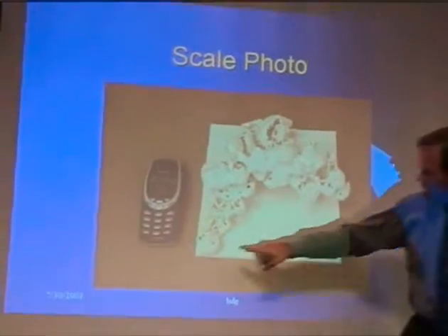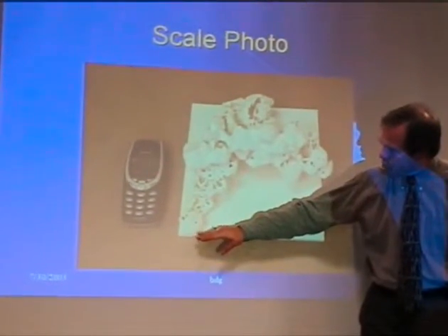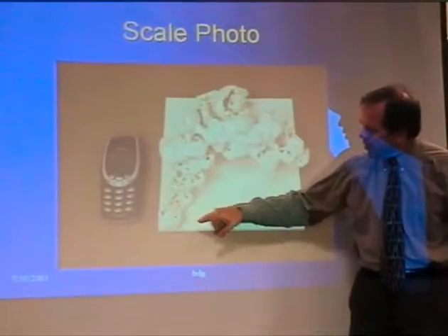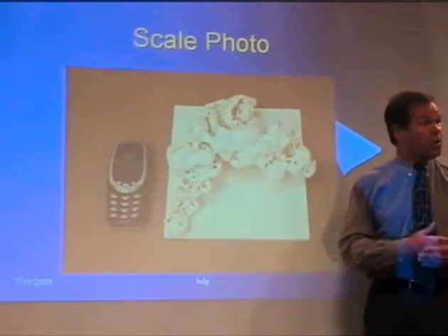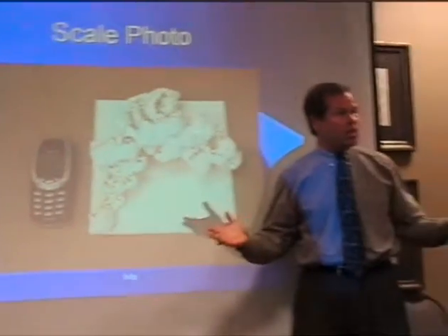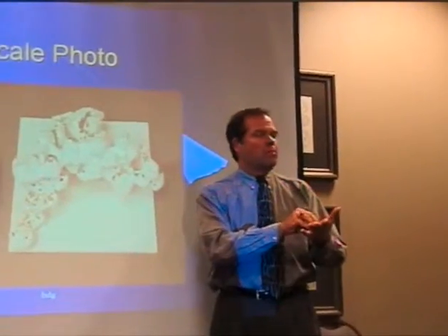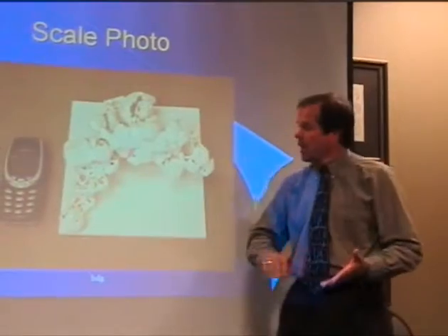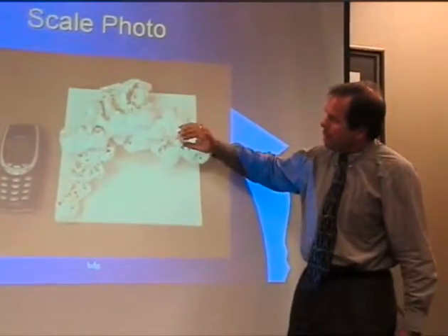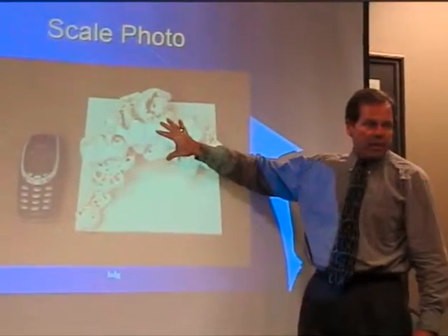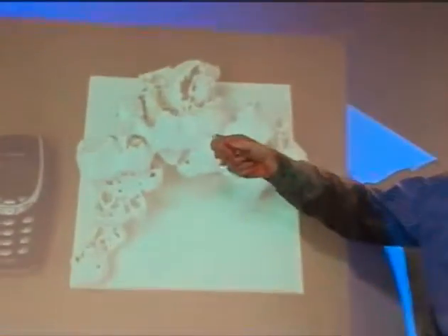So you'd have an instruction to the print head: spray here but not here. Just like you do with an inkjet printer. This is really an inkjet printer, with adhesive which is binding small polymer particles together. And then this is all built up. This stage is fairly fragile. If I would bring that model here and you would start to handle it a lot, you could break it.